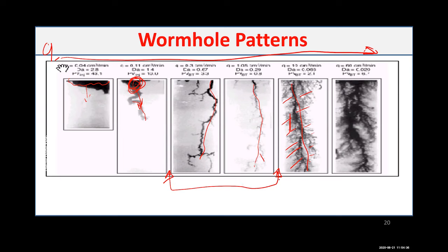Also, if you go away from the optimum, you pump a lot of acid, but you only create the certain length that you need for the wormhole to dissolve. So you do not get any additional benefit. All the acid that dissolves more, you remove the oil, you remove the rock, but you actually do not get additional benefit in the permeability part.